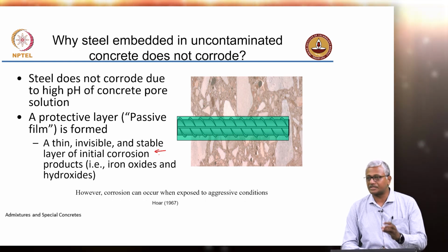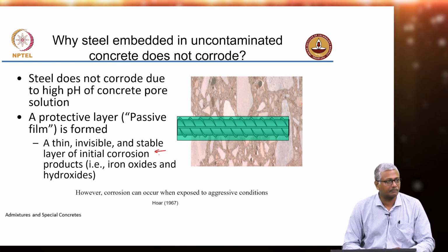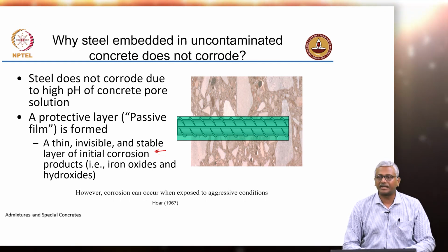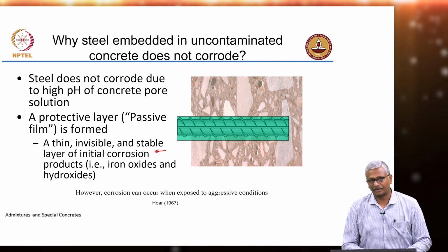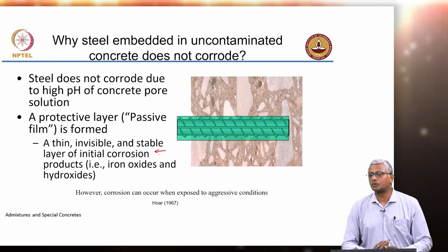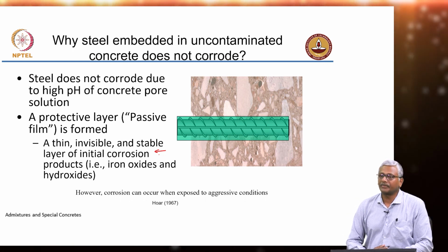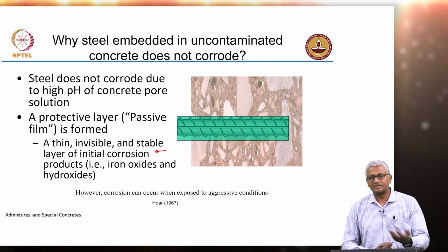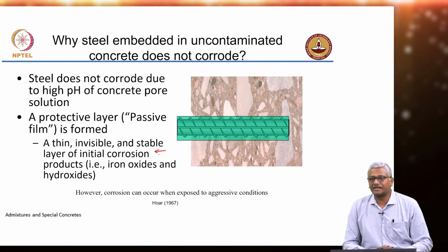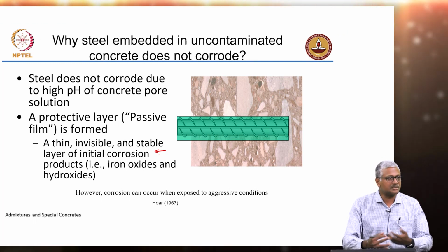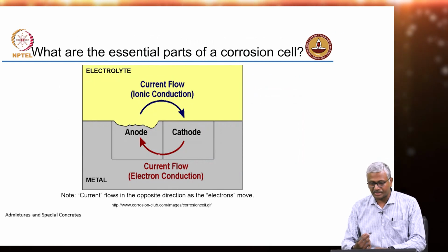And this corrosion resistance enhancement is primarily because the passive layer that forms on the steel surface in the alkaline environment is much more stable in the case of the corrosion resistant steels, especially in the case of stainless steel. Okay. Stainless steel is expected to not corrode for a long time. It does not mean it will never corrode, but for a long time, if the conditions are ideal, stainless steel will not corrode. But reinforcing steel typically has a tendency to start corroding because of change in the environment in its vicinity, okay. So, let us see what happens which leads to that change.